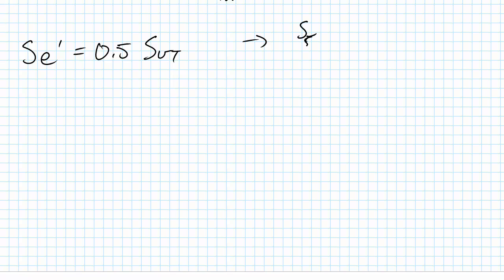Well, we know the hypothetical endurance strength is going to be about 50% of the ultimate strength. So we need to know the ultimate strength. This is just a material property which we can look up. And the ultimate strength of this steel that I mentioned, according to the back of the book, is 90 kpsi. So our hypothetical endurance strength would be about 45 kpsi.